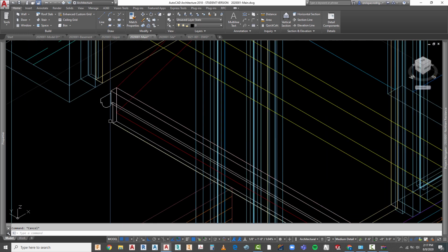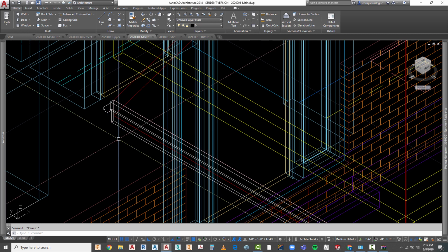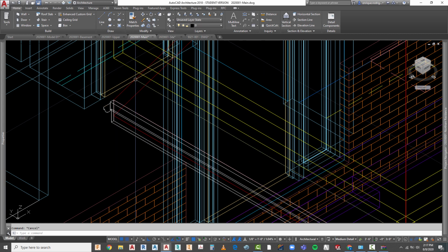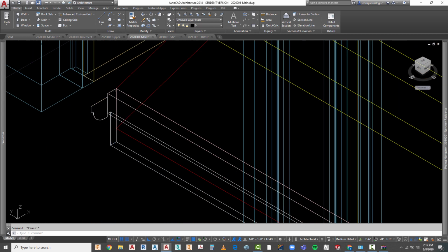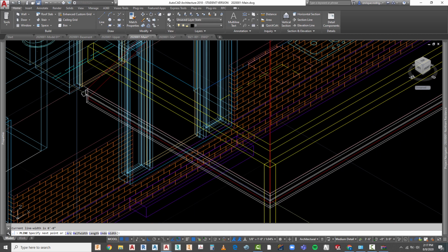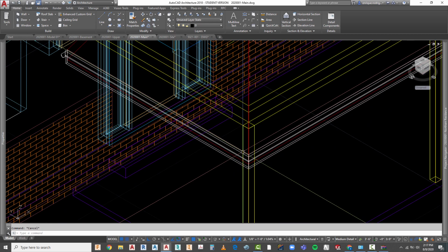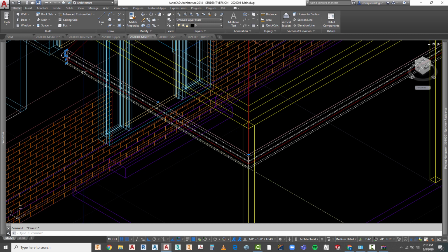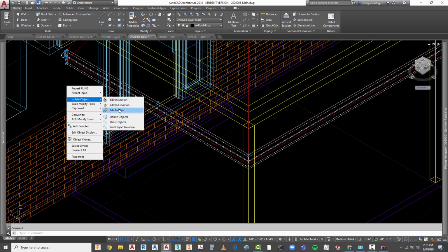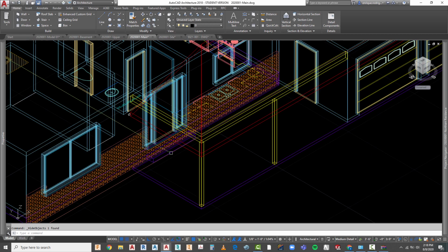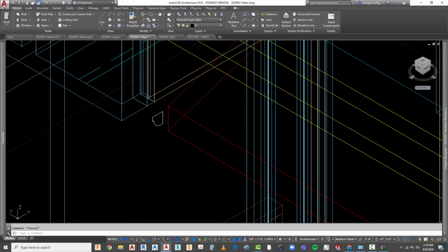And what I need to do at this point is duplicate what we were doing in terms of our path. So in this case, I'm going to start from this corner right here and create a polyline exactly where we were before. I'm going to hide my fascia board at this point. Just hide the object, not the layer, because this is in the same layer.